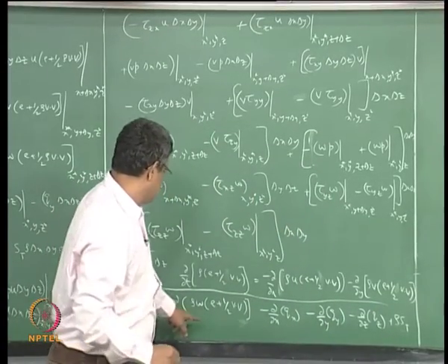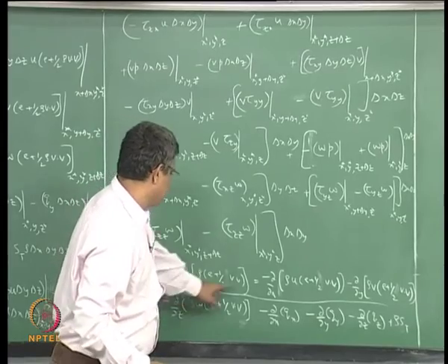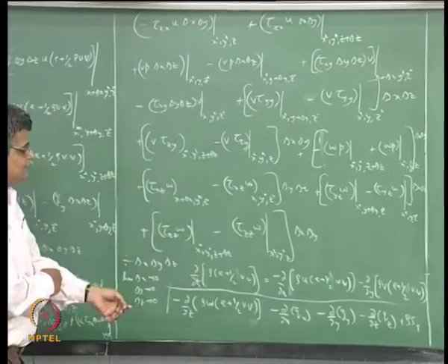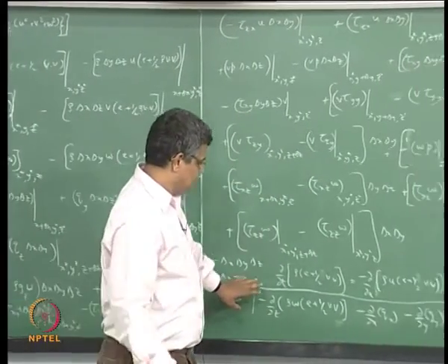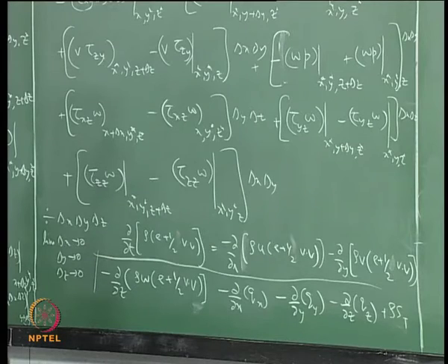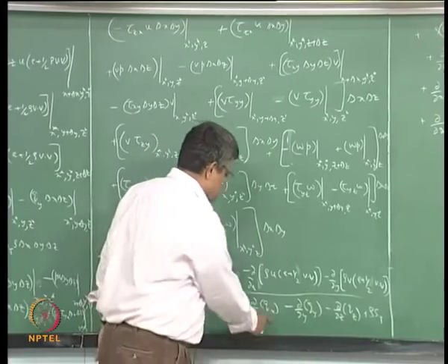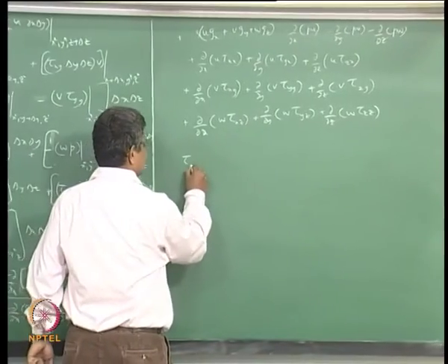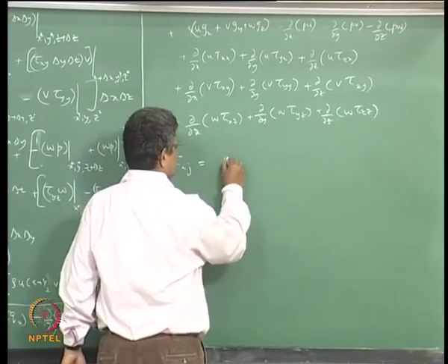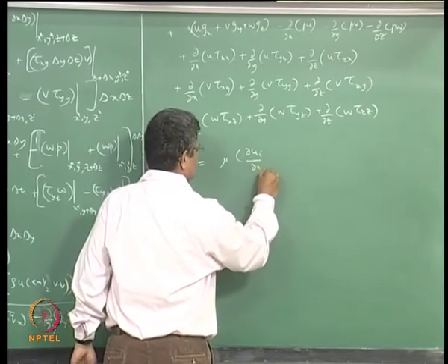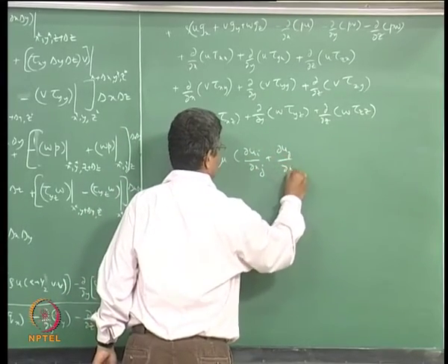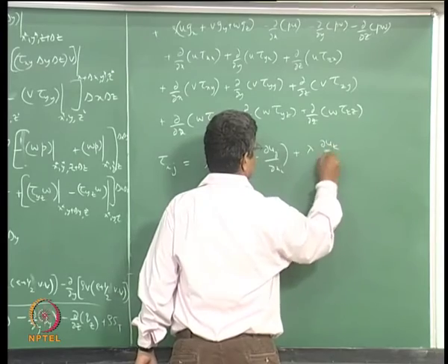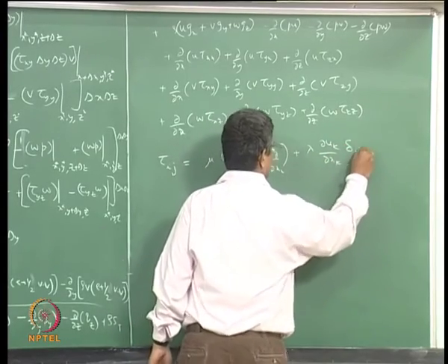and as usual we can bring this to the left hand side, and then we can write this. As of now this statement is not complete because we have not specified what these heat fluxes are. We know what the stresses here are. We can say that τij for a Newtonian fluid is μ times (∂ui/∂xj plus ∂uj/∂xi)